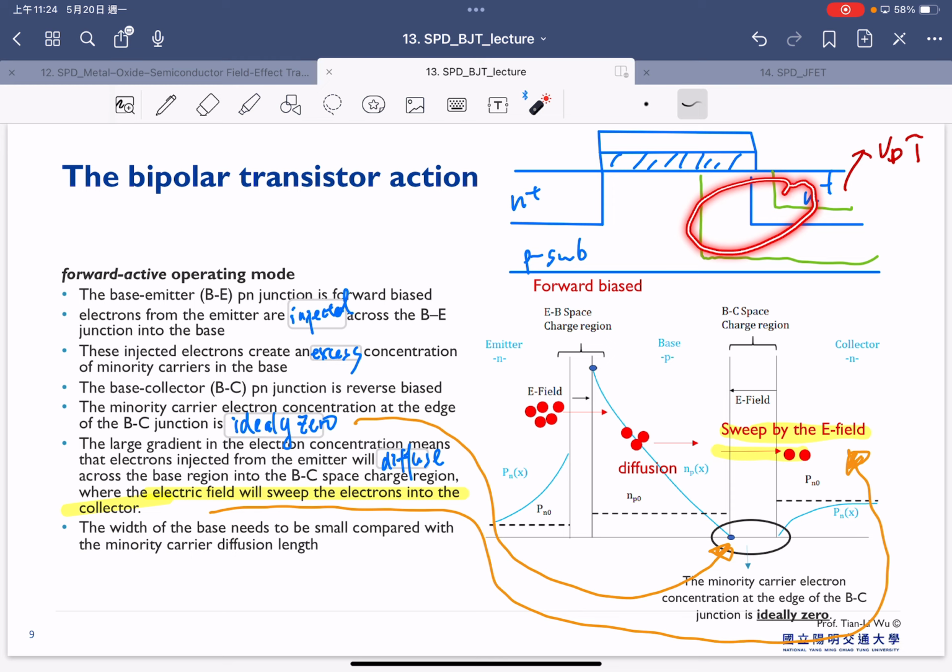And as you know, there's a moment once we apply the gate bias, but our VD is large enough, our channel becomes this way, right? That was already mentioned before. The channel will be pinched off because right now your VGD is smaller than VTH, so your channel will be moving from the drain side to the source side.